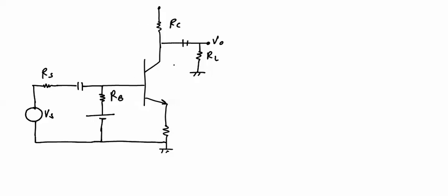Now in this amplifier, common emitter amplifier, this time RE resistance is unbypassed. When RE resistance is unbypassed, during AC analysis we have to consider the negative feedback that is provided due to RE. The formulas are a little bit changed due to this emitter resistance RE in the circuit. The approximate hybrid model will be like this.